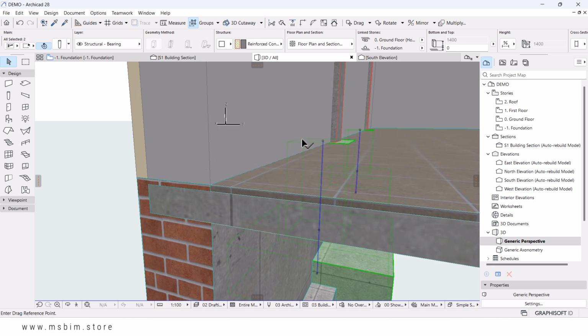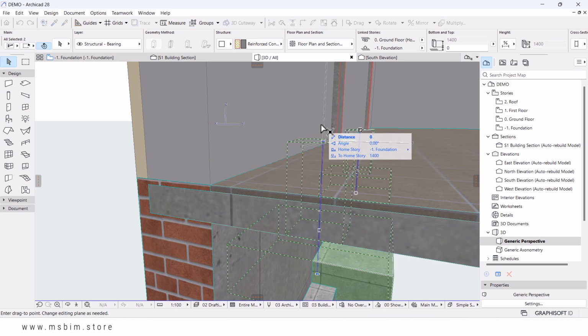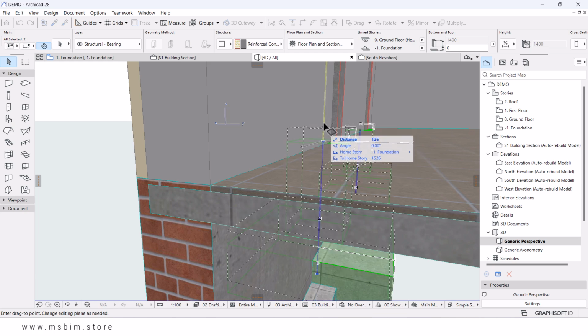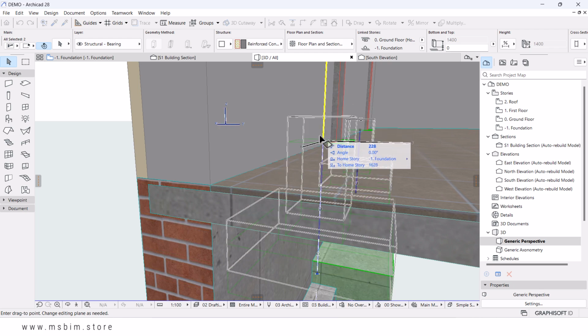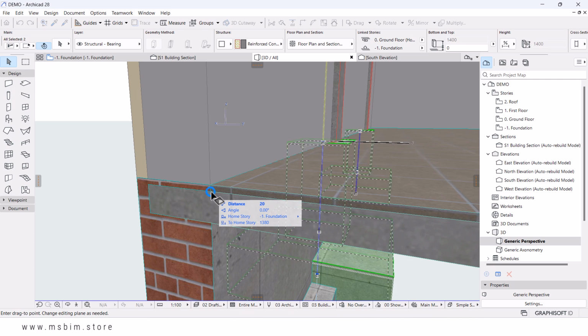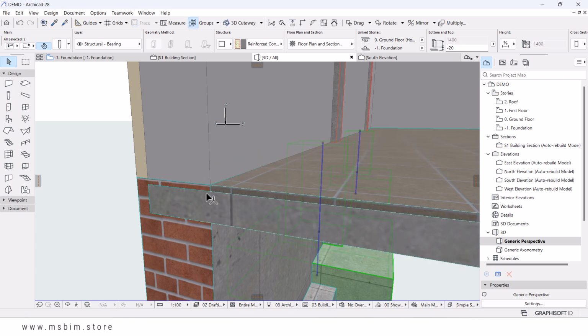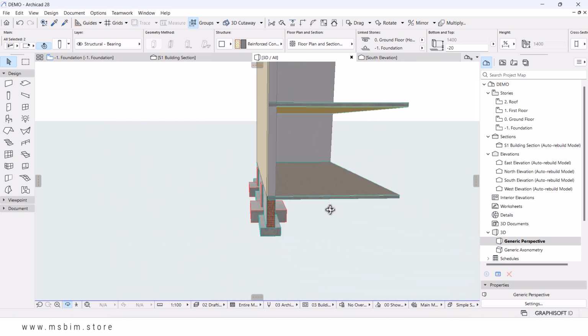So I'm going to drag this by Control D and drag it vertically. Make sure you hold Shift on your keyboard so that you can restrict it within this yellow guideline, and then I would move it right underneath my floor tile. Perfect. That's how it should be